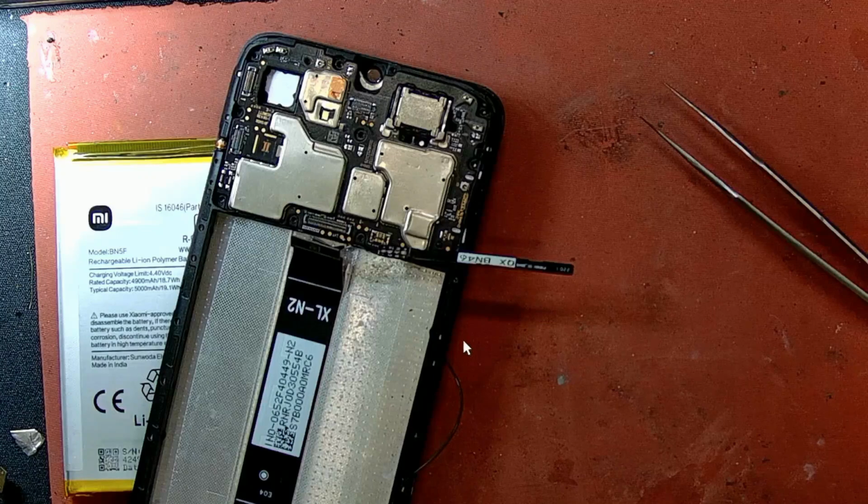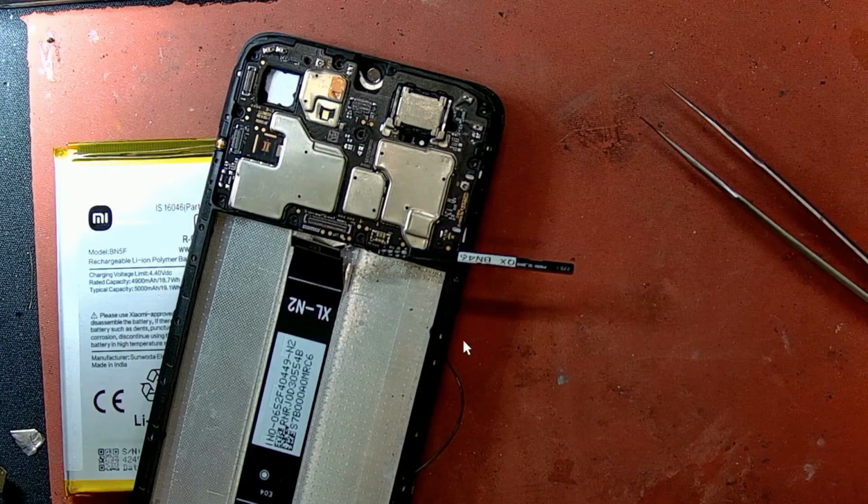These readings, as I already told you, are only for a clue. I need to say, not for judgment. For confirmation, you use other tools like a multimeter, USB ampere charger, DSO, these types of tools. So do not rely on one tool. I hope you get my point. In simple words, in Android phones, you do not rely on one tool.